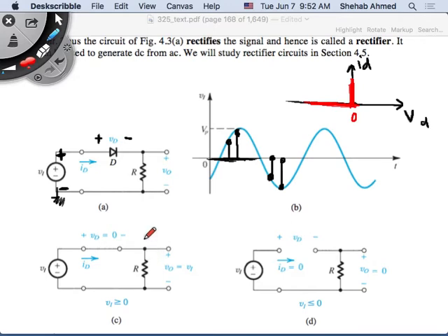In reverse, you have a V value. Here, I have V values, right? Here in forward, I have V equal to 0. As soon as I have 0 plus a small voltage across it, then I can theoretically conduct an infinite amount of current. Basically a short circuit, right? So that's why it's modeled as a short circuit when it's forward biased.